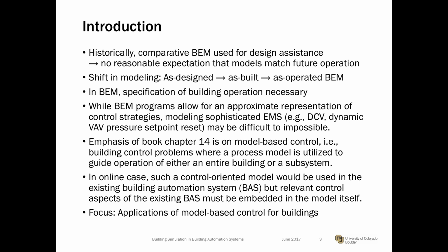Increasingly, we expect more fidelity of a building energy model, and to achieve that, we need a specification of the building operation. State-of-the-art building energy modeling programs do allow for some representation of control strategies, but really complicated, sophisticated control strategies like dynamic pressure set point reset, or demand controlled ventilation that captures the occupancy in the building, are a little harder to model, if not impossible.